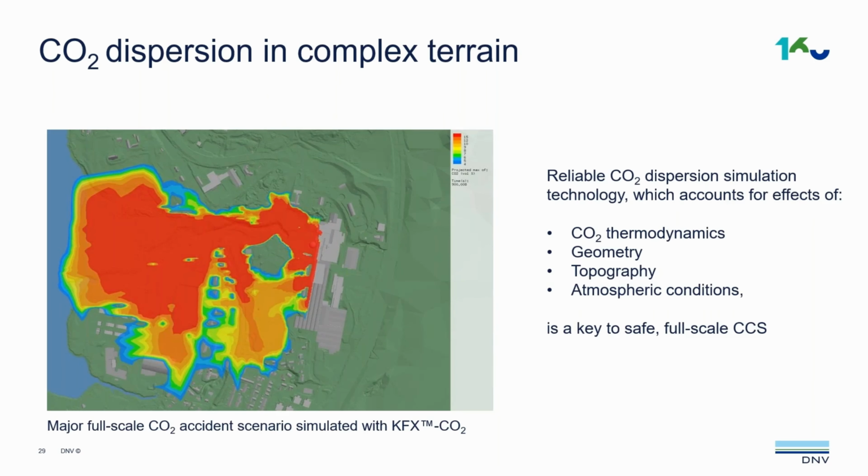So this is a snapshot of the same simulation. This is at 15 minutes from the start of the release and from above. It shows the projected maximum of CO2 concentration ISO contours. The red zone, which as you can see is quite large, represents a concentration of CO2 higher than 15 volume%. We have observed that when taking into account multi-phase release, higher concentration of CO2 is maintained for a longer time.